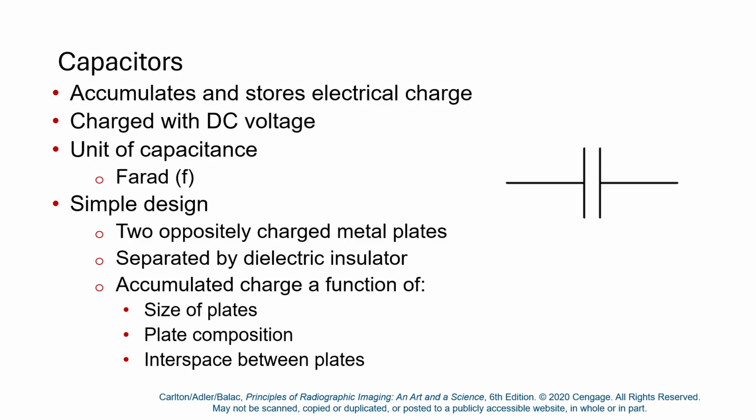Okay, and instead of getting high voltage from a high voltage transformer, you do have a step-up transformer, but you just keep stacking stored voltage in an array of capacitors. Okay, and then when you make the exposures, you bleed out the stored voltage as extra charge on the line. And so tube current is maintained, but voltage is sacrificed. And I think the book talks about a capacitor discharge: you get a drop of voltage as soon as the capacitors are bled out of charge. So in a capacitor discharge machine,